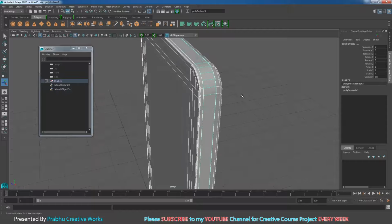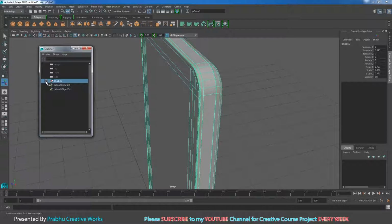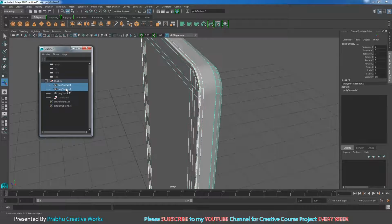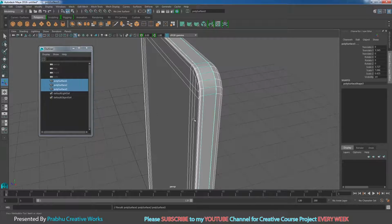That means the 3 parts will be separated as each and every piece, like this. It will automatically happen in your outliner. So I will extend this group. I will use control and select these 3 meshes and use shift P to unparent. That means it will leave that group. Now I select all 3 poly meshes, go to edit, delete by type and choose history. So the group will be gone.